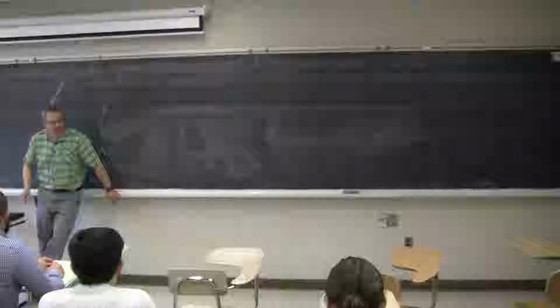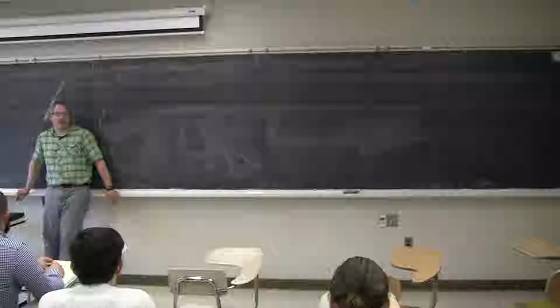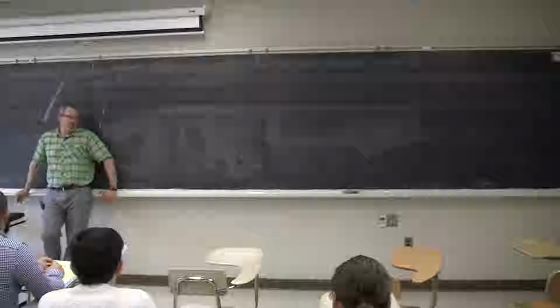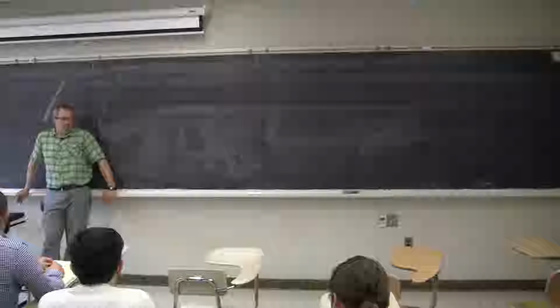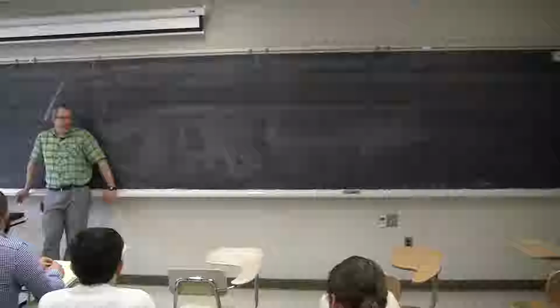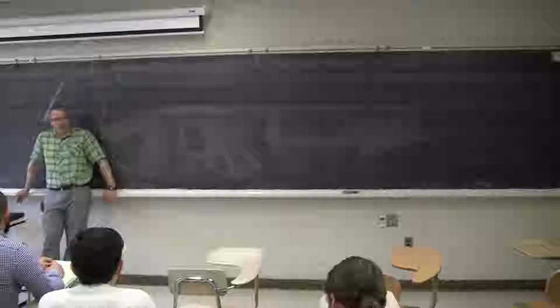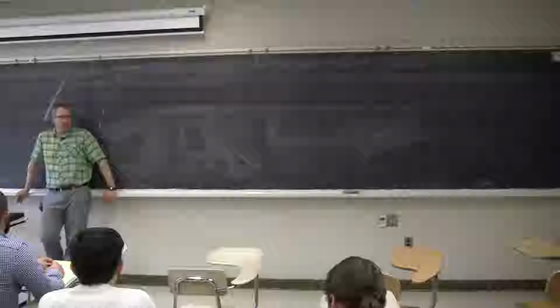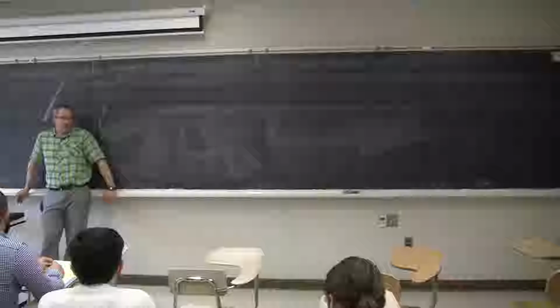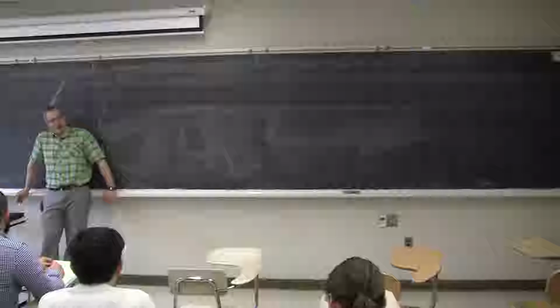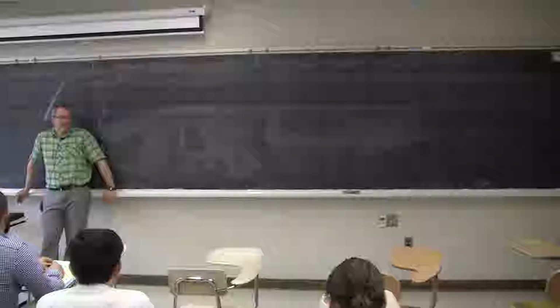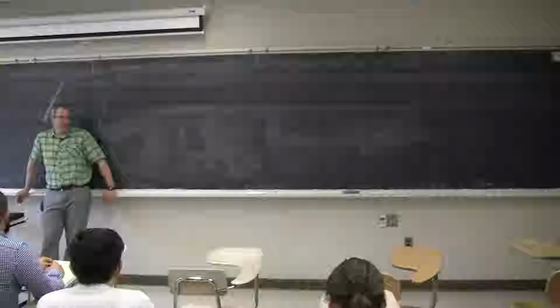When you multiply v(t) times i(t) and do all your trig identities, you end up with a VI magnitude times the cosine of the angular difference between theta V and theta I. That's the real part. Then the imaginary part was the negative VI sine of the difference in angle.